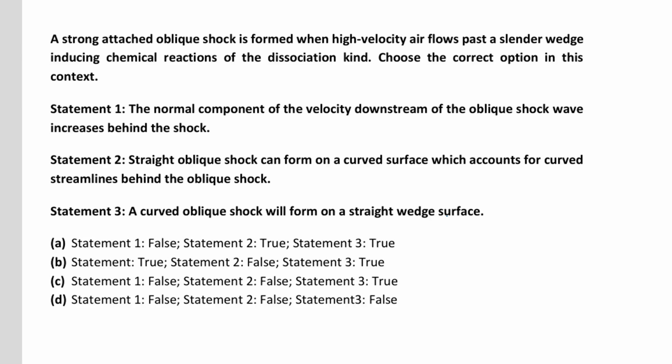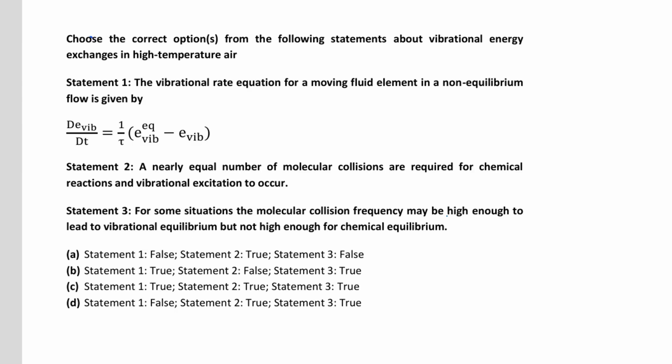Okay. First we will see statement 1, which says the vibrational rate equation for a moving fluid element in non-equilibrium flow is given by this equation. If you see this equation, this is the correct equation: dE_vibrational/dt equals 1/tau times (E_vibrational equilibrium minus E_vibrational). This is true.